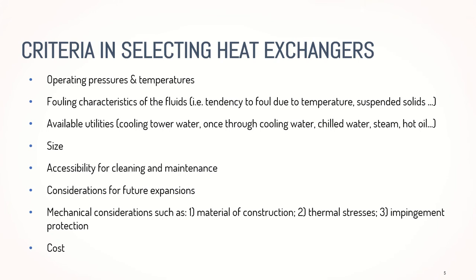So whether we have cooling tower water, or steam, or hot oil, and also the size, what size do we need for the heat exchangers, and also the accessibility for cleaning and maintenance. As you can see, shell and tube needs cleaning and maintenance, and also consideration for future expansion, mechanical considerations such as material of construction, thermal stresses, and impingement protection, and the end would be cost.